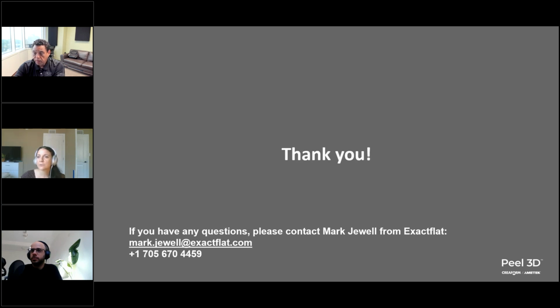Sure. So from Dustin, we have, for use in the marine canvas world, what's the total range for scanning? Say we had a top that is 14 feet long, 8 feet wide, 6 feet tall. Can we navigate around this with the scanner? You could potentially do this. You would have to make sure you're placing targets all over the part, since it is mostly flat and mostly large and wide. So these targets, you'd be placing them around like every 4 inches or so. So you could still do it. It would just take a long time to place those targets down.